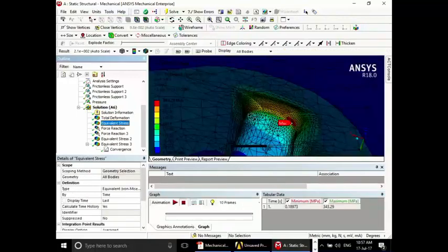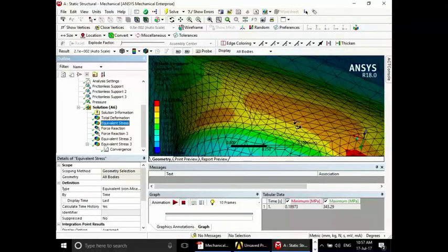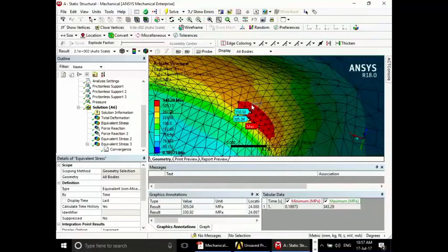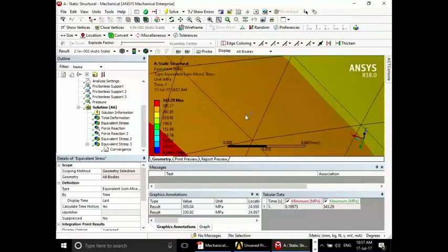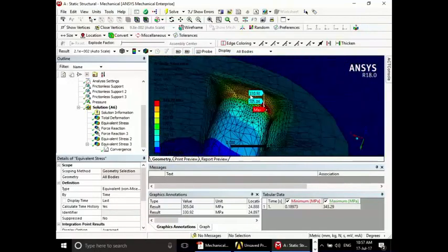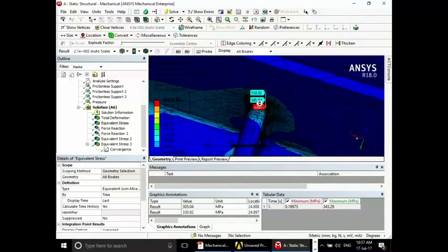Okay, so if I look at my stress there, if I probe across 1 or 2 elements, you can see that there's a much lower percentage change across one element. Okay, so you generally don't want to make your mesh fine everywhere to capture that level of detail.